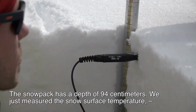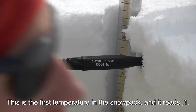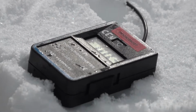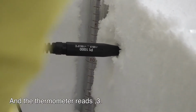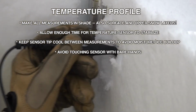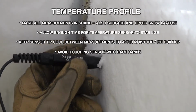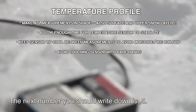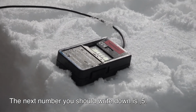We just measured the snow surface temperature. The next measurement we take is at 90. And this is the first temperature in the snowpack, and it reads 0.1. And we go down to 85, and it reads 0.3. The next number you should write down is 0.5.